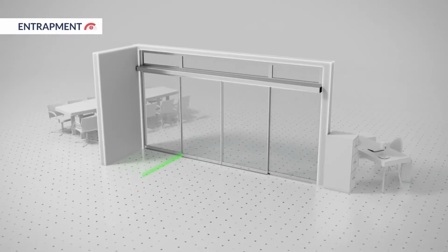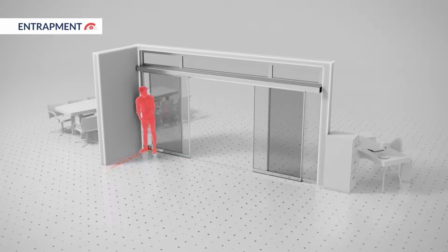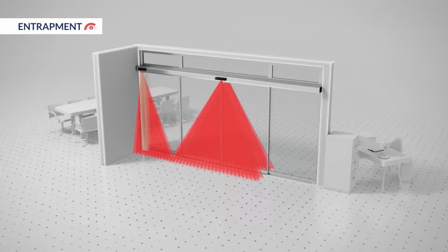However, there is an exception where a full safety coverage is needed, even in a tolerated risk environment. If the distance between the wall and the moving leaf is less than or equal to 20 centimeters, the related side screen must be safe to avoid crushing risk using an IXIO S or a structural means of protection or low energy movement.